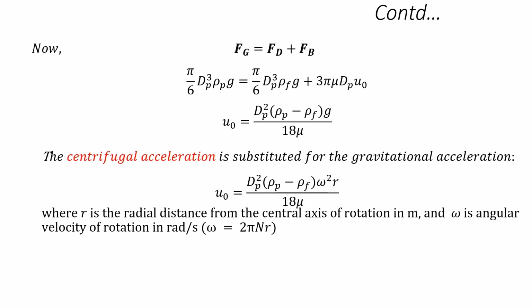Now, we will put these three forces here. This is rho p, the gravity force F g, this is rho f, the buoyancy force, and this 3 pi mu dp u naught is the drag force F d.